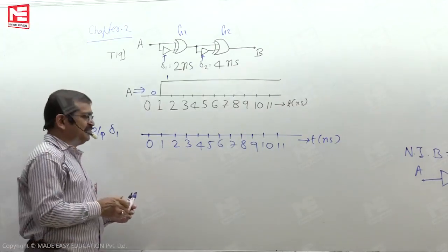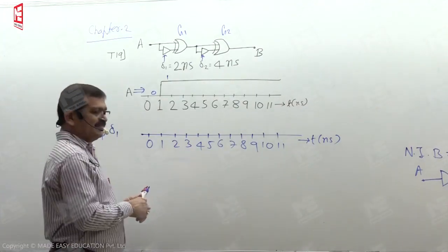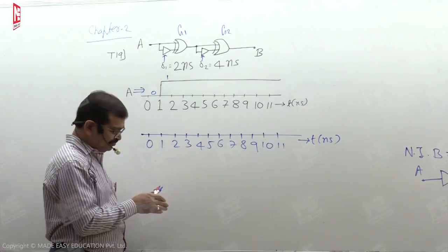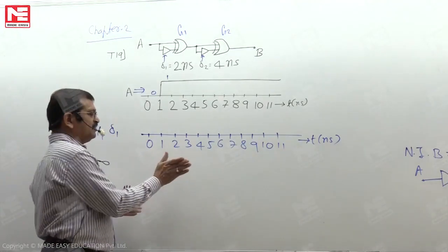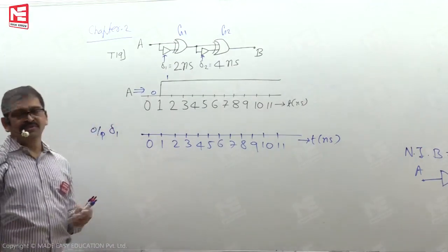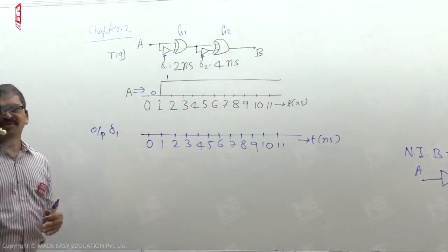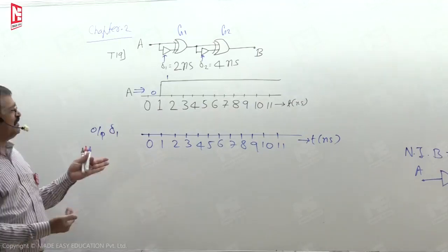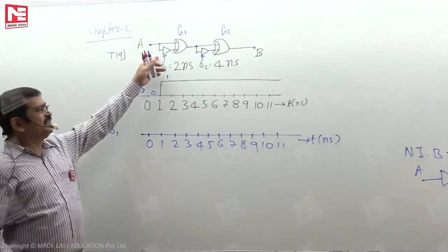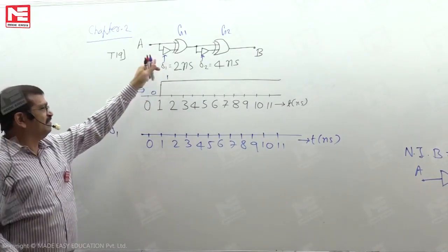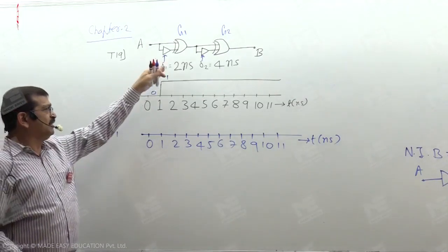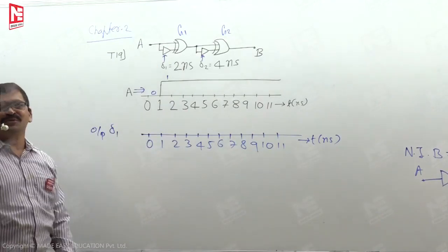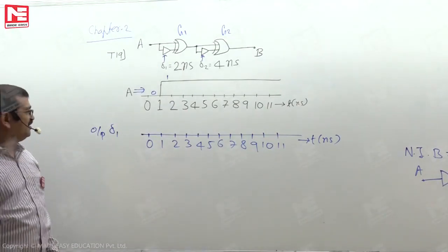So based on this, see, if you are sleeping, somebody is hitting you, you may not wake up immediately. You may take some time to wake up. The same thing is happening here. This gate is sleeping. When this gate is hit with this waveform, it is responding only after 2 nanoseconds, something like this.